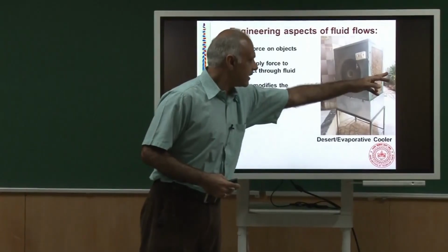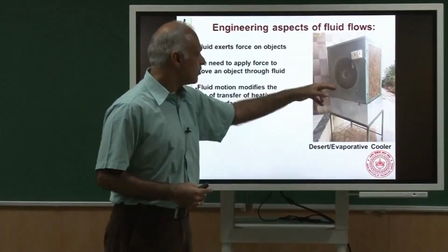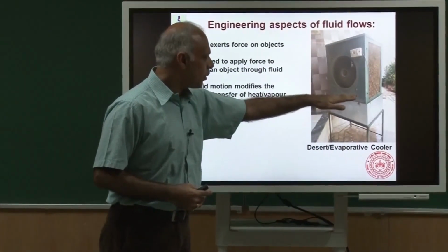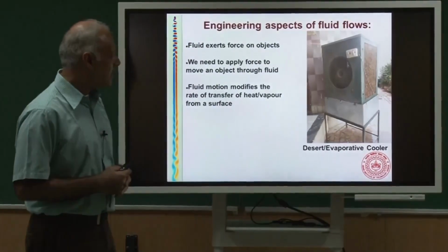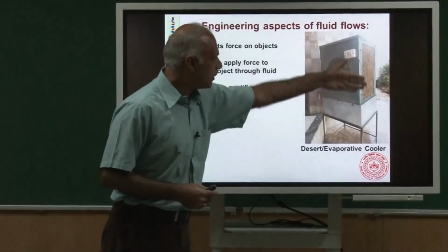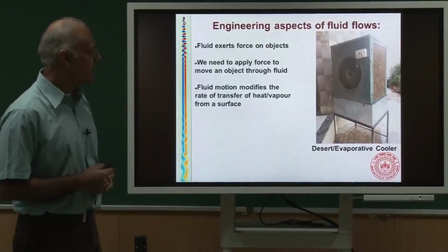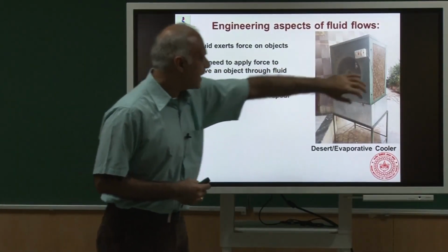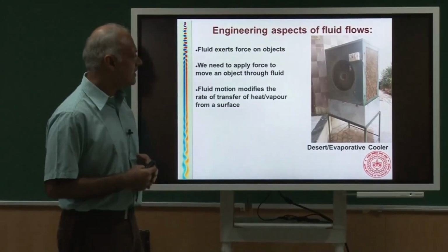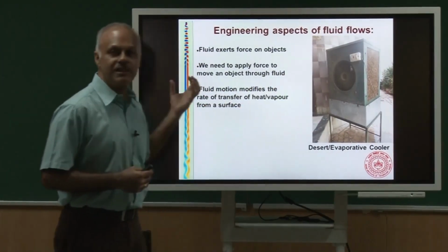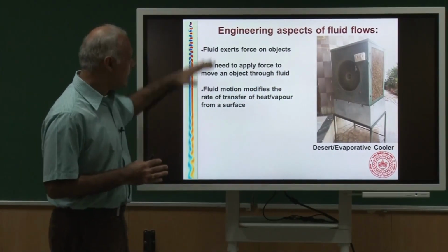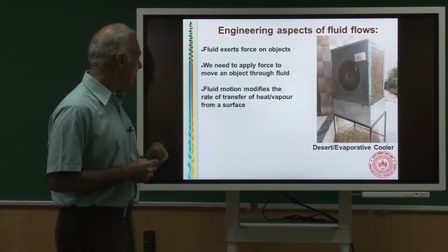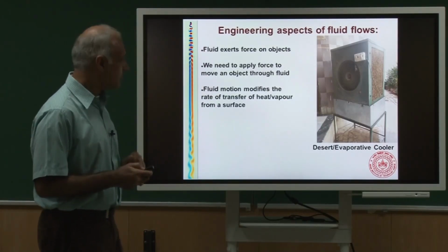So, there is a breeze that is sucked in. You put in energy, there is water inside this cooler, and there is a pump which sprays the water at the side screens, and then when the air is blown, it is sucked from the outside through the side screens, and then you get a cool stream. So, you can see all these coming into action, including the heat transfer and the vapor transfer.